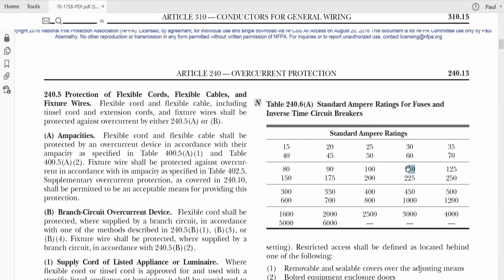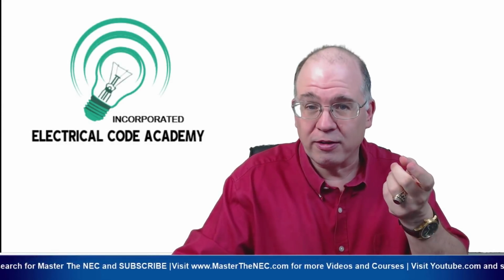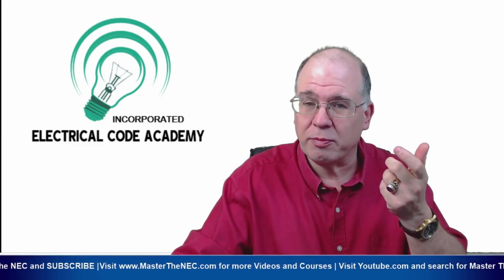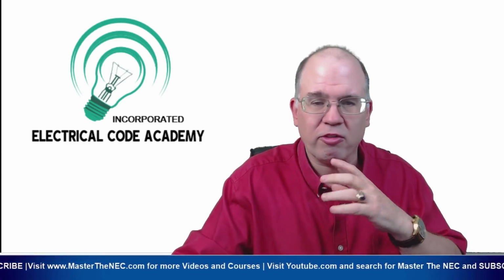Well, this is good for 110. That ain't going to work. It's got to be at least rated for 115. So here, a 125. That would be the selection of our overcurrent protective device for our circuit. Again, that is only based on the variables that we've discussed so far. We haven't done any adjustments and corrections based on ambient temperature and the number of conductors. We're simply looking at terminal ratings based on what we've been presented so far.